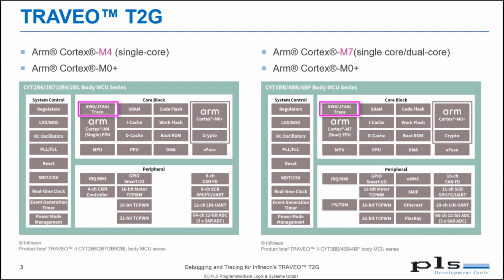For the debug tool, the CoreSight subsystem provides, for example, hardware breakpoints and also triggers. These hardware breakpoints and triggers are used for providing basic debug functionalities in hardware, so that we can, from the debugger, use these capabilities for breaking the system, for providing single-step functionality, and also especially with the triggers for synchronizing the debug actions when we have multi-core configuration of the devices.